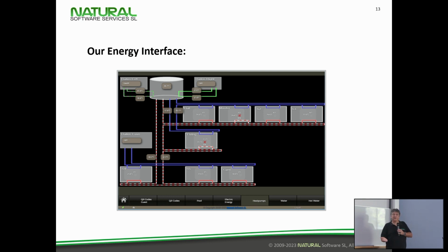And we had to change some simple things to achieve this. In one project, for example, we had 80% autarky of the house. Everybody was thinking, well, this is really good. And then we found out that the pool circulation started at 8 o'clock in the morning and was using about 2 kilowatts of electrical energy.